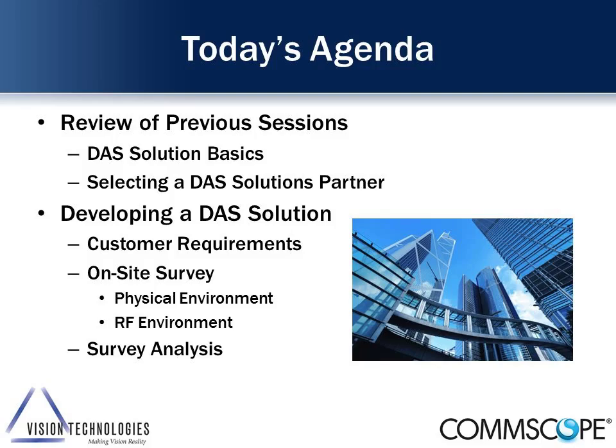Okay, thank you, Virginia. Appreciate it. Thanks everybody for joining today. The agenda for today, we're going to do a quick review of our previous sessions, and then we're going to talk in more detail about developing a DAS solution in terms of the customer requirements specific to the on-site survey, in terms of identifying the physical environment we're talking about, as well as the RF environment, and the analysis of what we have discovered.